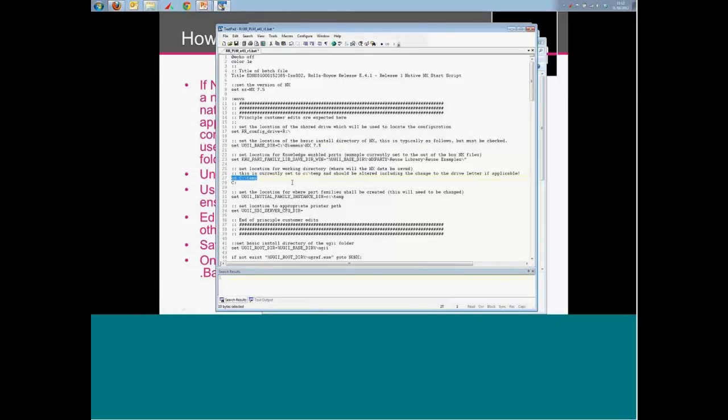This section here is the working directory. Where would you like to create the data for NX? That's totally down to you, wherever you would like to put that. I'm going to just set this to R and delete that and put a switch on here. The /D changes the device at the same time, so you can CD /D to this folder.